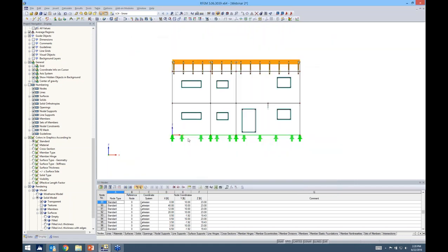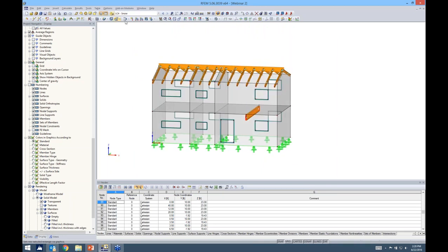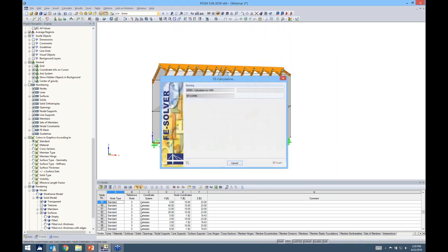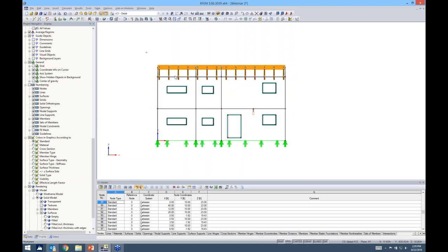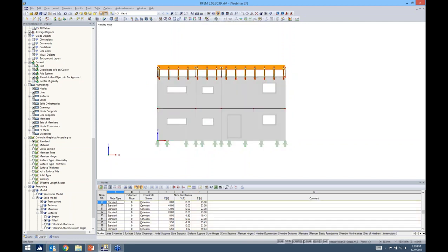Okay, so I can click OK out of here, and you'll notice that my drop-down box, which previously was empty, now has all of my load cases, and the program automatically created all of my load combinations according to ASD and LRFD. When you're applying loads, you want to make sure that this is set on the correct load case that you want the loads applied to. So I think what's easiest here is to highlight our floors and make this visibility based on the selected objects.